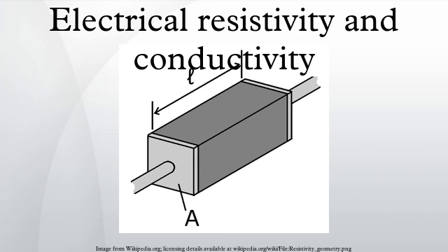Resistance versus resistivity in complicated geometries. If the material's resistivity is known, calculating the resistance of something made from it may, in some cases, be much more complicated than the formula above. One example is spreading resistance profiling, where the material is inhomogeneous, and the exact paths of current flow are not obvious. In cases like this, the formulas need to be replaced with an equation where E and J are now vector fields.